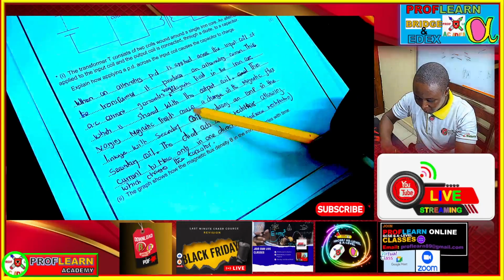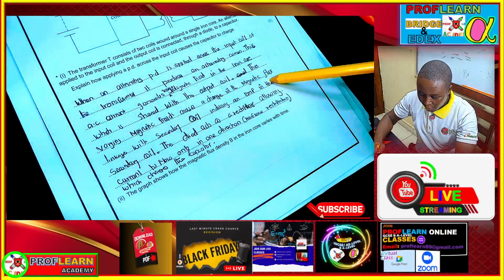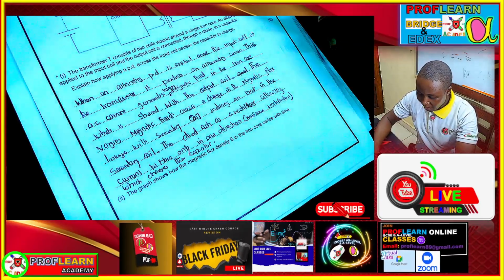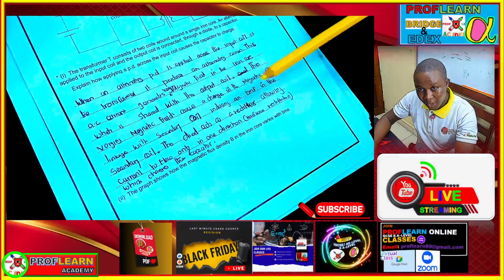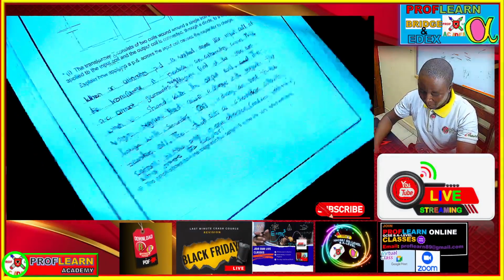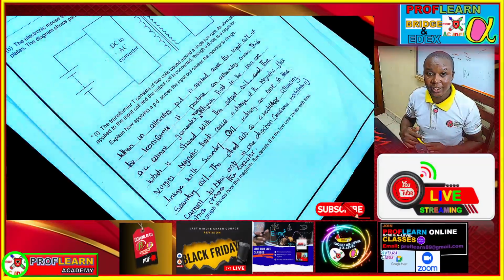The varying magnetic field causes a change in the magnetic flux linkage in the secondary coil, inducing an EMF. Yeah, so we are going to have an EMF here through electromagnetic induction. So the diode that we are having here is going to act as a rectifier, so that current is going to flow in one particular direction because it was alternating. So we shall have direct current that's going to charge the capacitor here. So basically that's exactly what you are going to do. Until next time, guys, we're gonna pick from there. We shall move to the next topic.